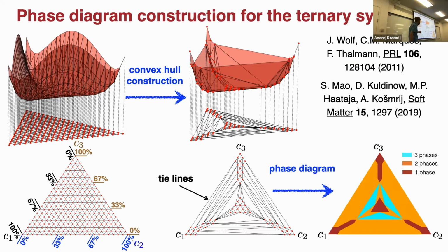So for example, in these regions we'll have 2 phases. One phase will be at the top corner, one at the bottom corner. These are also known as the tie line in phase diagram systems. But if you start in this region, we'll have a triangle that corresponds to the 3 phases. The compositions of the 3 phases will be these 3 corners, right? We can also figure out the relative volume fractions of each of the coexisting phases by just using the usual lever rule, which makes sure that the average concentration is the one that we mixed in the closed system.